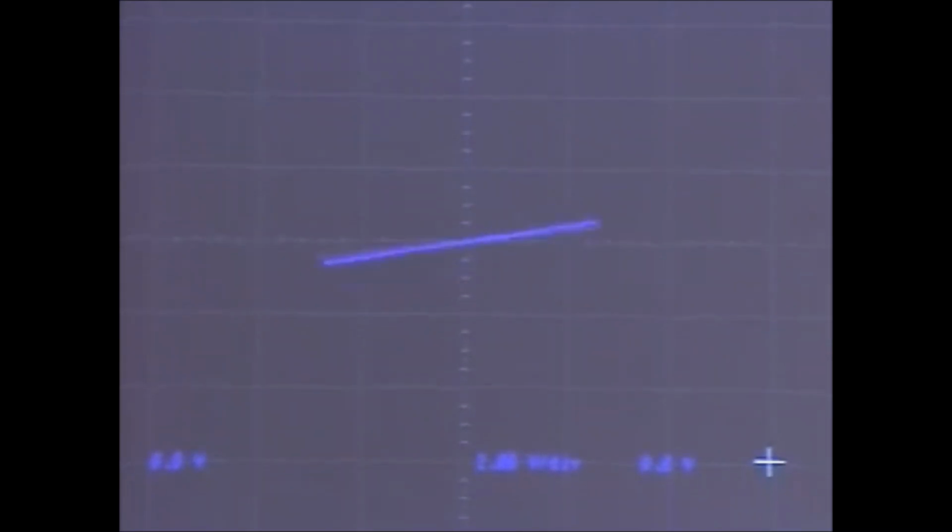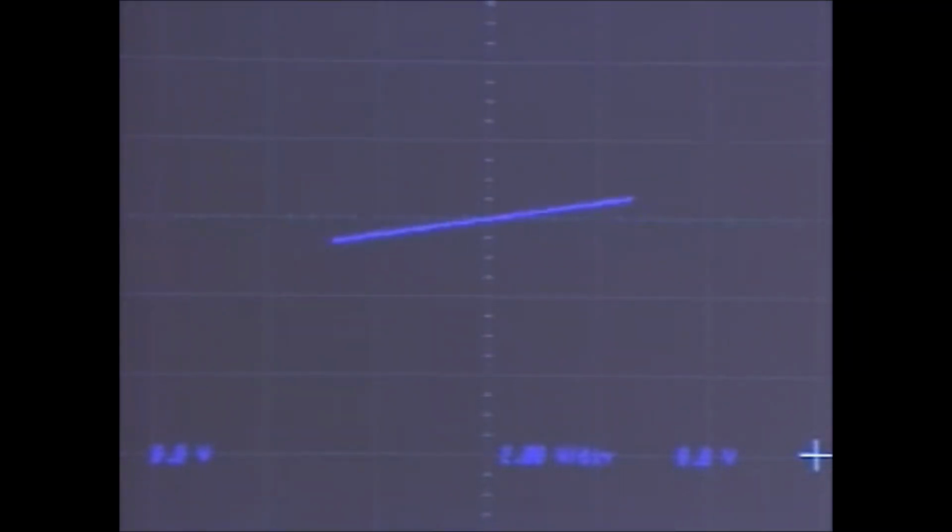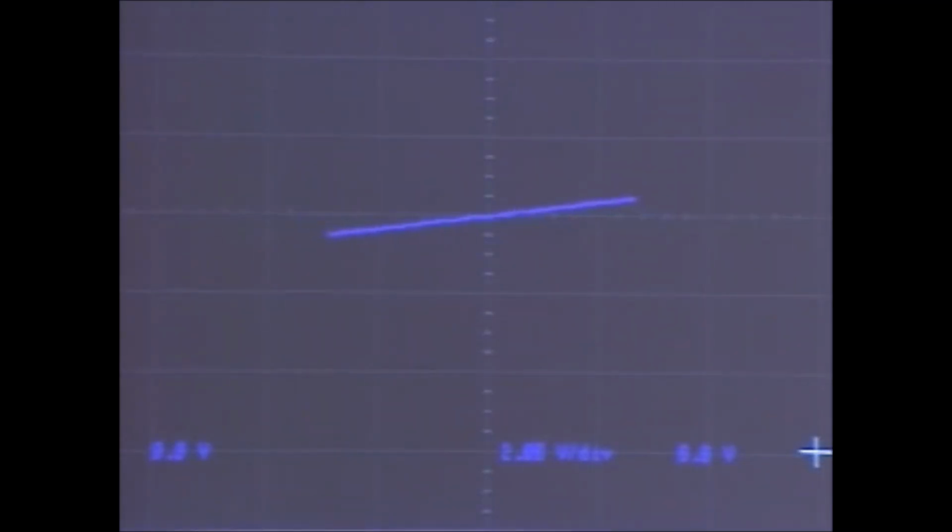Next thing is a photoresistor. It's a resistor. It used to be a resistor, Lorenzo. Oh, okay, that's fine. So this is a photoresistor, and notice that it almost behaves like an open circuit. But what I'm going to do is shine some light on it. When I shine light on it, it begins to conduct and becomes a resistor of some value. There you go. So that's a photoresistor.